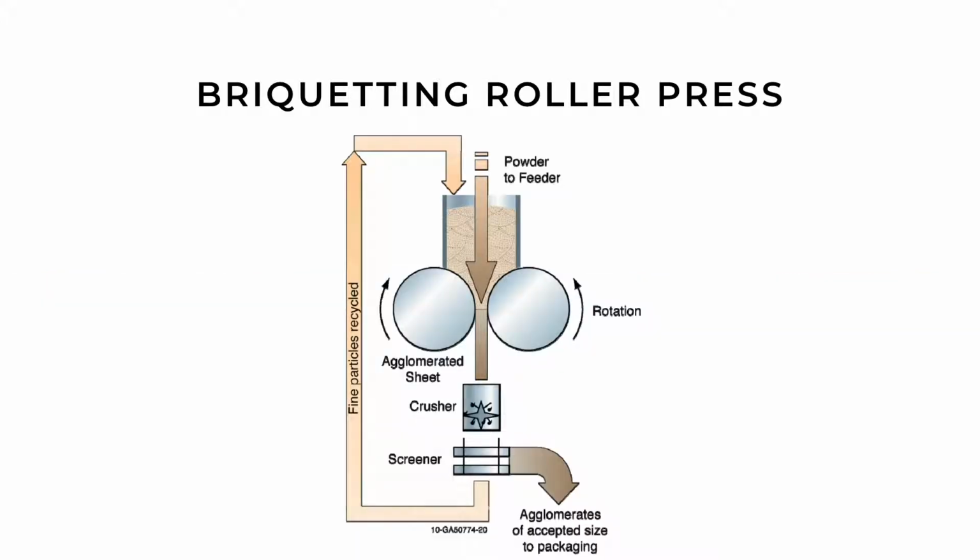In the briquetting process, the biomass is compressed under high pressure and temperature, allowing biomass particles to self-bond to form high-density briquettes. In a briquetting roller press, the feedstock falls in between two rollers rotating in opposite direction and is compacted into pillow-shaped briquettes. Briquetting machines can handle larger sized particles and higher moisture content without the addition of binders compared to pelletizers.